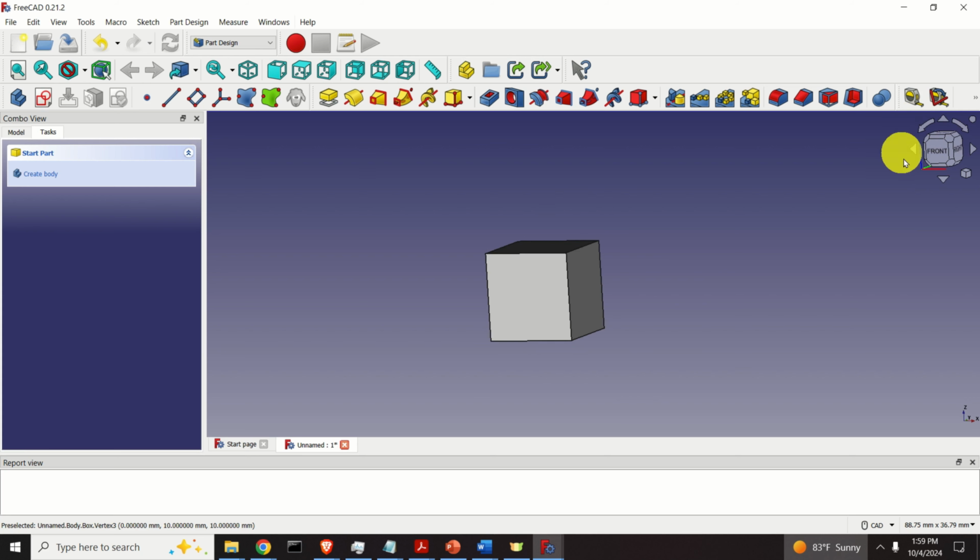Consequently, click here, that is, click on this edge, and then click here, that is, click on Constrain Horizontal Distance, and over here let's select 300, and here it is. Now you can see that the height is 140 and the width is 300. Good. Our next goal is to extrude this base. For that purpose, you need to click here to close, and you will be back in this 3D view.